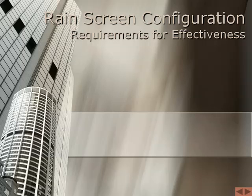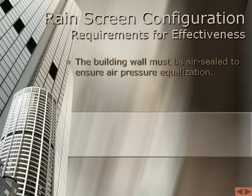Rain screen configuration. Requirements for effectiveness. For the rain screen to function effectively, it is important that the inner wall be airtight. If there are leakage points or openings in the inner layer, the pressure in the cavity will not equalize with the exterior air pressure, and subsequent rain penetration can easily occur. However, it is easier to permanently seal this inner layer than it is to seal the outside veneer surface. The inner seal will last longer because the inner wall layer is not exposed to harsh exterior surface environments.